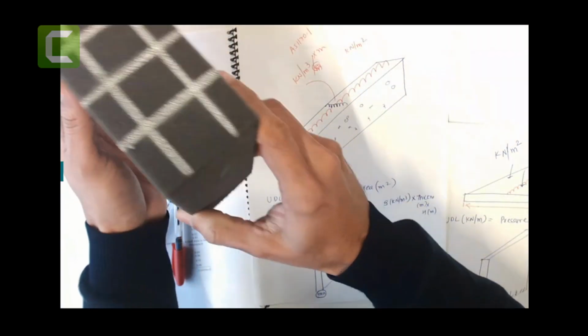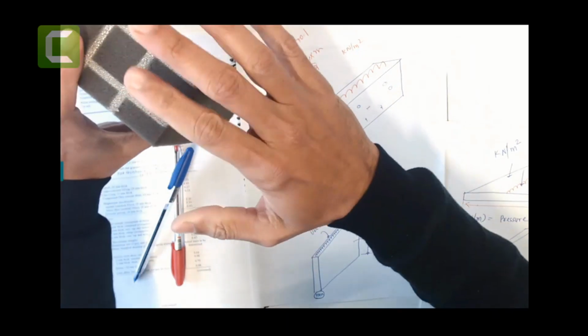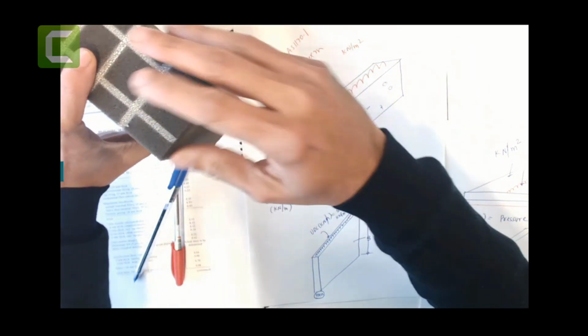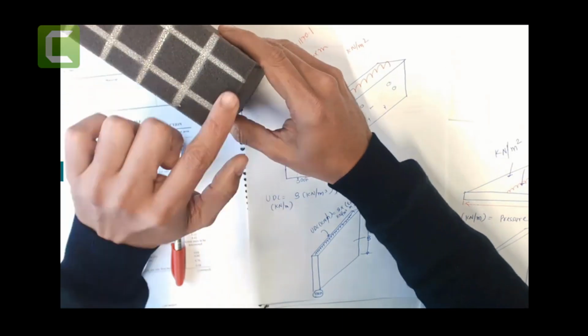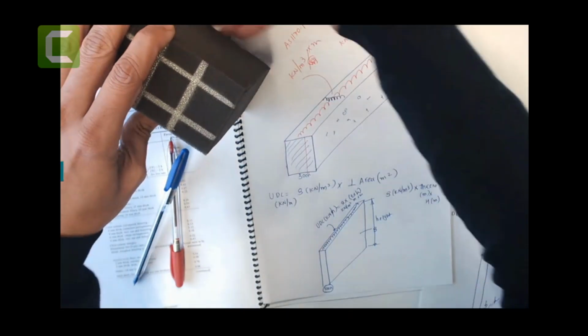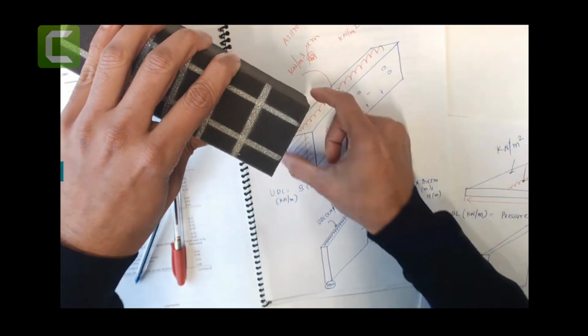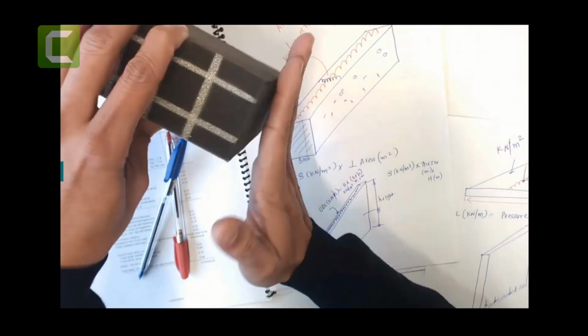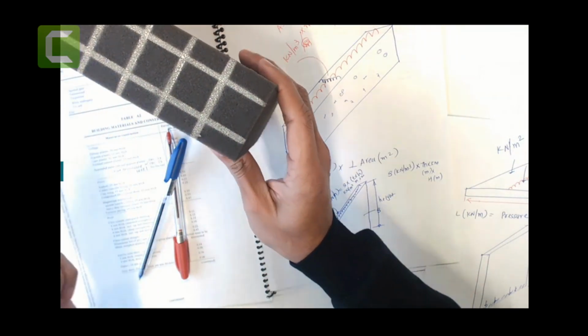Okay, so if I have this kind of a block, there's a formwork. If I sit it down, this will apply the line load. You can see this will apply the line load. So density of this times this area, that's what you are calculating if I want to calculate the UDL load in that fashion.